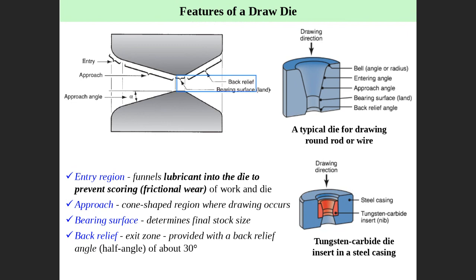I would like to keep the die away from that. So this is a relief. Relief is to exit freely without being in contact with the die. This is whatever we call relief or clearance.